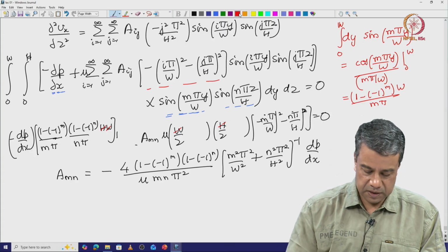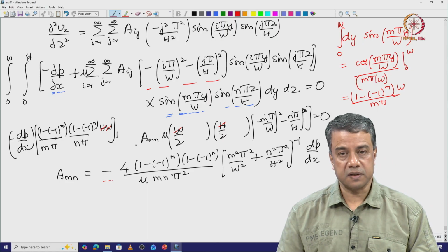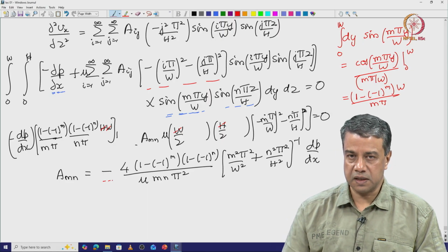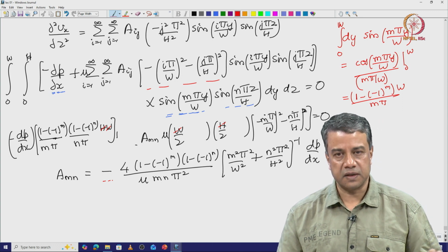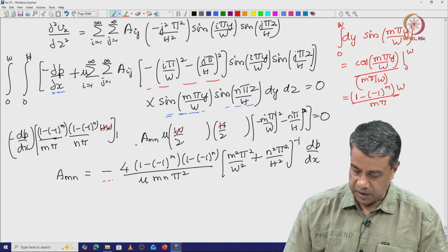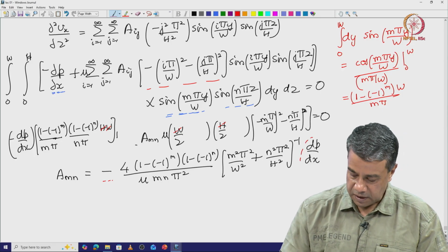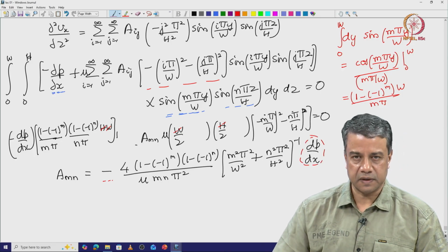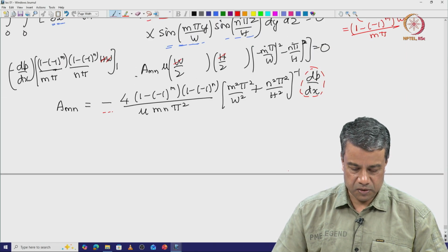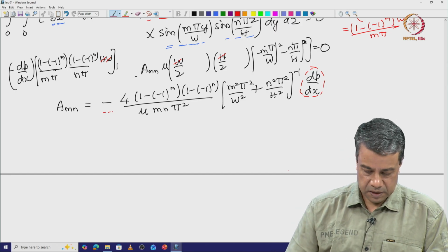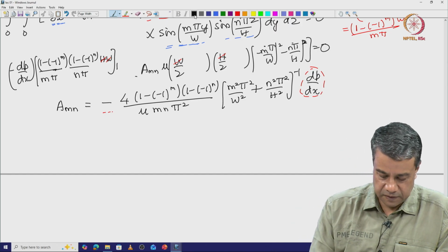Okay. Recall this negative sign. That is because for the flow to be in the positive direction, dP by dx has to be negative. Pressure has to decrease with x, so that Vx is positive. Therefore, dP by dx is negative if Vx is positive. That is because the flow has to be down the pressure gradient. So, this gives us the solution for the velocity field.